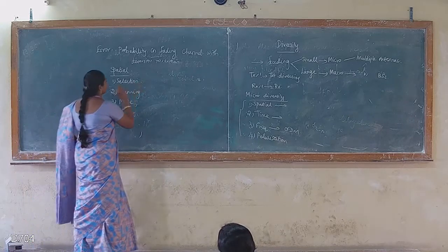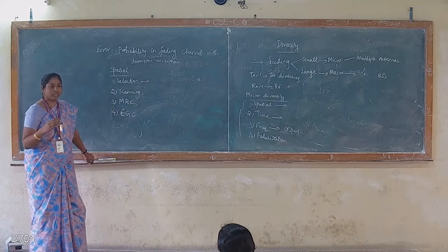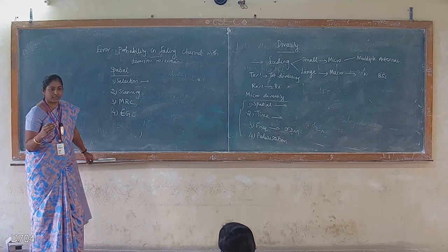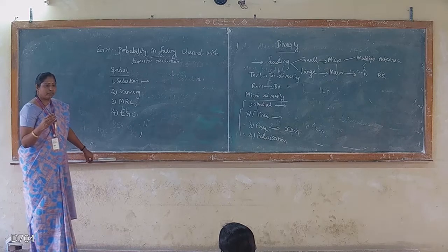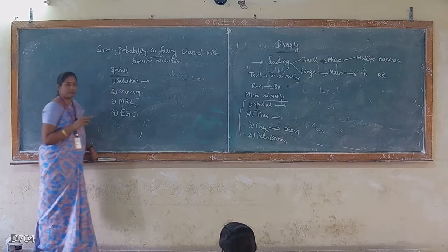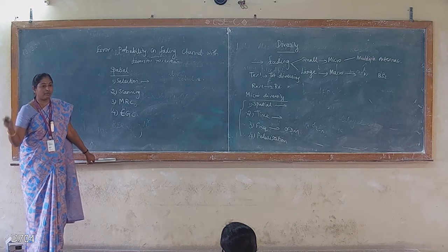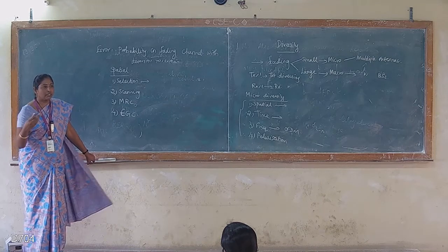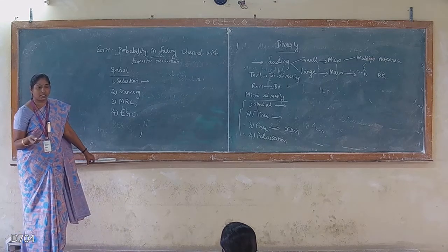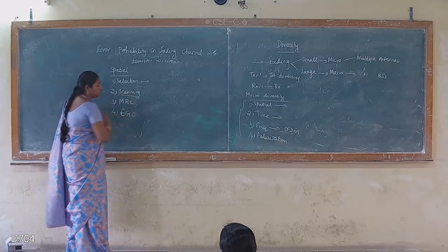So what is the principle of selection diversity? In selection diversity, the receiver is having n number of antennas. So the receiver is having the n copies of the transmitted symbol. Okay. So from that the receiver can choose one of the best copy. So that is the principle of selection diversity. So we have n number of antenna branches, but only one branch is effectively communicated to the receiver. So other branches are not a part of the receiver. So there is wastage of resources in the case of selection diversity. Okay. So for that we are going to the next one, scanning diversity.